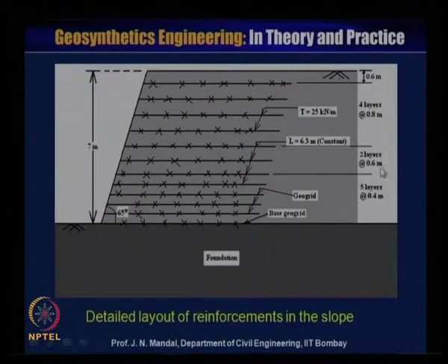We are giving 5 layers at a spacing of 0.4 meter, then 2 layers at a spacing of 0.6 meter, then 4 layers at a spacing of 0.8 meter, and the remaining you can provide with 0.6 meter.